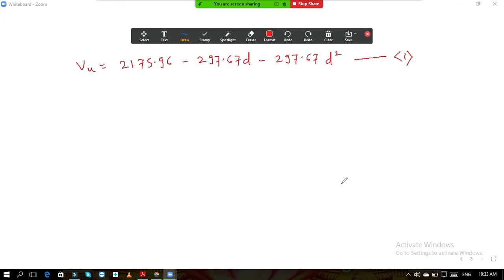So now in footing we want to avoid the placing of stirrups. So we should provide a depth to the footing in such a way that the concrete present in the footing resists all the shear force. If the concrete alone resists all the shear force, then there is no need to provide shear reinforcement.